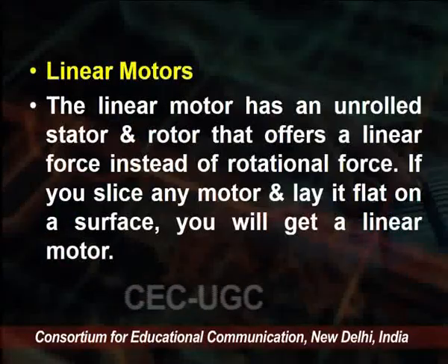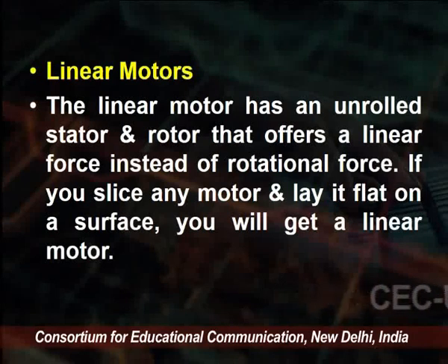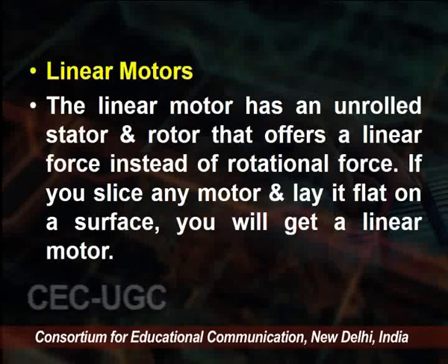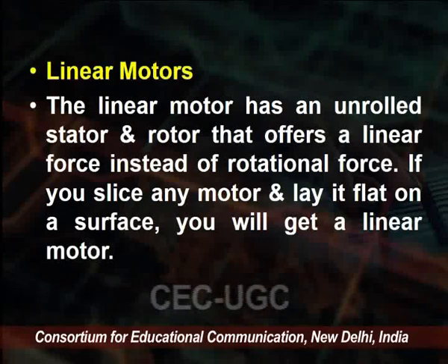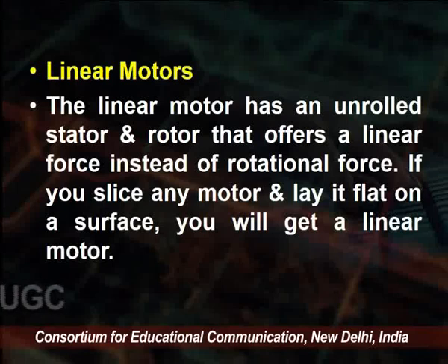And another type is the linear motor. The linear motor has an unrolled stator and rotor that offers a linear force instead of a rotational force. That's why it is a linear motor, because we are using linear force. If you slice your motor and lay it flat on a surface, you will get a linear motor. So this is another type of motor.